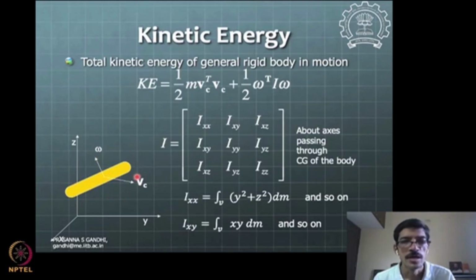So you just see the rigid body in motion. It may be part of some mechanism or part of a robotic system or whatever system, it doesn't matter. We just see a center of mass and ask the question, what is the velocity of the center of mass of that rigid body, and the kinetic energy is defined as half mass times v transposed into v for the center of mass. This vc is the velocity of the center of mass. So it's like half m v squared, but generalized now into this form, for the rigid body, or in general a motion in 3D space.